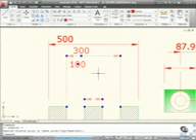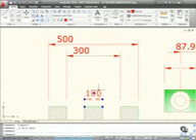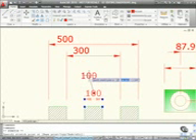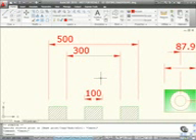Let me just hit escape there a second, just to lose that, and I'll undo that last step. So I click on there, click on the grip, and look, it just moves on its own. That's because we've used move text alone. Now let's have a look at that. What does that mean? What does that do?